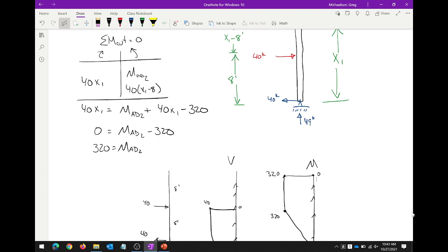So like a simply supported beam, uniformly distributed load, I want the deflection at midspan. Then what you can do is define a function from 0 to L over 2, integrate, multiply by 2. Then you can do that.